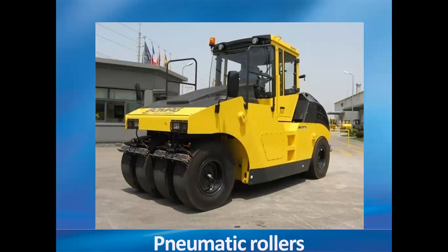So here we can change the type of rollers we are using. We can have tires of 4 numbers or 6 numbers, and a drum arrangement can also be made for these pneumatic rollers. An adjustment can be made, and the drum weighs about 2 to 8 tons, so that the conversion of these wheeled rollers can make the pneumatic rollers.